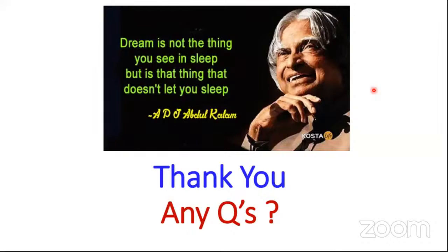Melting will only happen at the top surface but not at the bottom surface in the thickness. So usually the ballpark figure for this layer thickness is around 20 to maximum 40 microns for most of the materials. We can't go beyond that. So that's why this process also takes a bit longer time, because you are melting micron level layer thickness, right? And that is, as of now, a bottleneck, but people are working towards increasing the build rate.